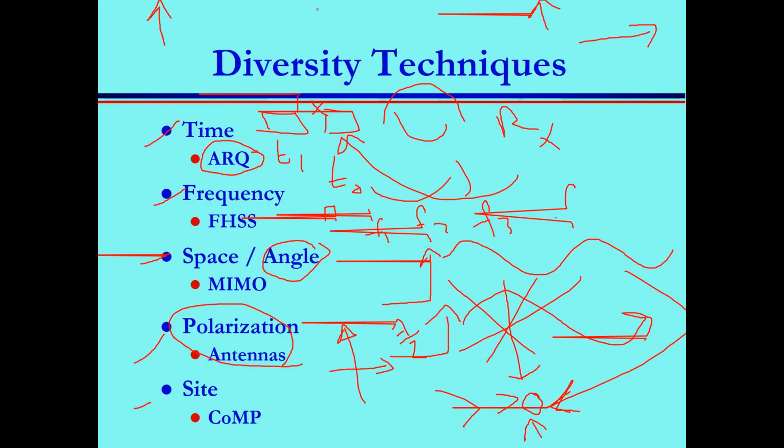The channel is not rich, it doesn't have too many reflections to give you all types of polarization. Just the polarization you use at the transmitter, you see at the receiver. And if you are not using the correct polarization, you lose your data. Well, for multipath channels, like the current channels we are using for Wi-Fi and LTE, 4G, 3G, you send your signal, the signal is rich in multipath.